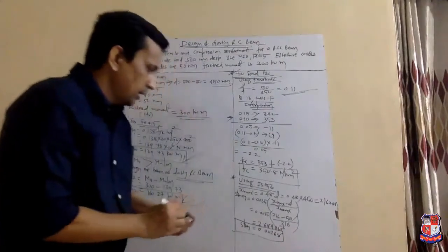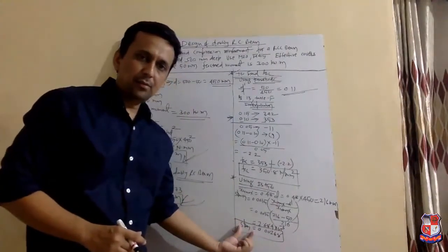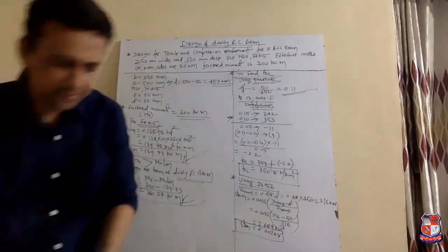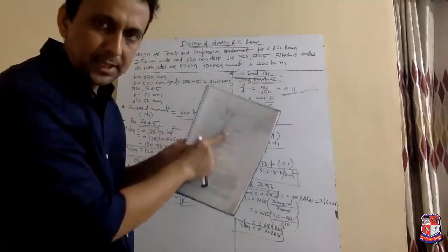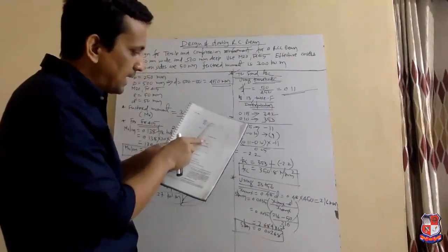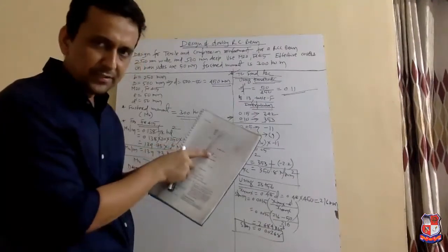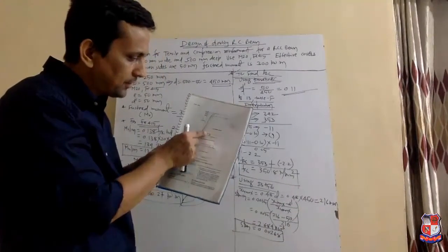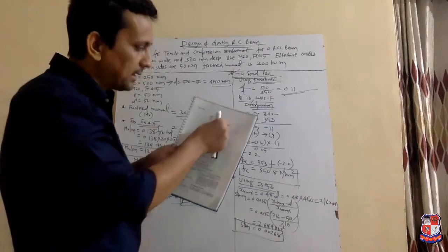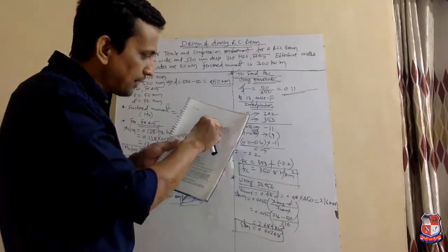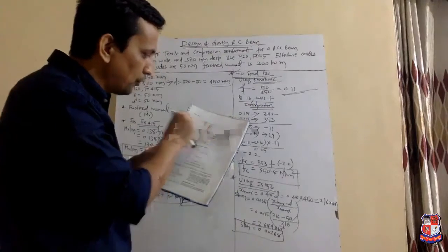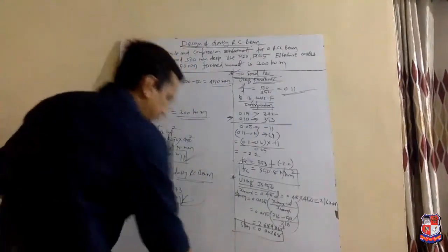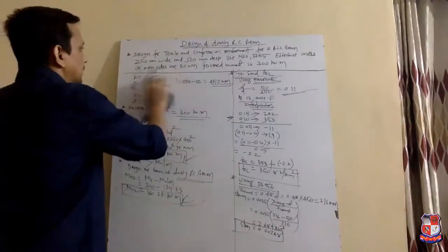Now, with respect to this strain value, we need to find the stress from IS 456, page number 70, graph 23A, right? So in the graph, the strain value 0.003 is given. Here we have 0.0027, so it is slightly nearer to 0.003. Just draw the parallel line, and when it intersects the Fy upon 1.15 line, you will get approximately FSC right here.